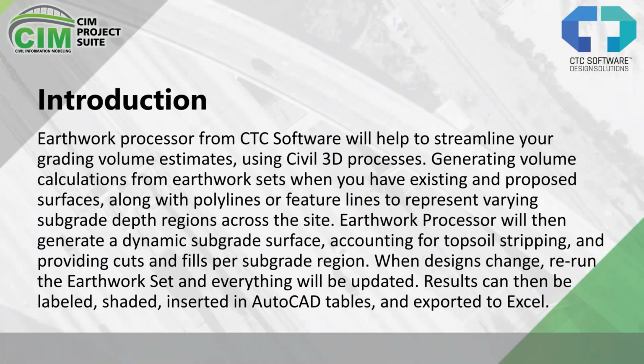Okay, Earthwork Processor. Some of the things it will do for you: it will help streamline your volume estimates by generating calculations from earthwork sets that you create when you have existing and proposed surfaces, along with polylines, feature lines, and/or survey figures to represent varying subgrade depth regions across the site.